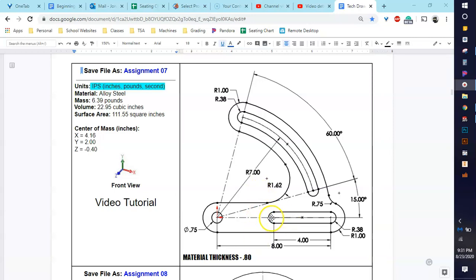So I am actually only going to use the straight slot for this. This portion down here, I'm going to be drawing with just normal lines and arcs. And then this up here is actually a center point. Okay, it's off of the center, but it's an arcing slot. So that's what this is. This bigger piece is also the same thing. And yes, we will trim that. So you'll get to see how, when you're trimming slots, it deletes your relations. So you'll see why I didn't do it down here. But I'm going to do a mixture of the two so you can see both. You're welcome to try this as a slot. Maybe you think, hey, it's not that bad. I'll just tell you that there's more things you have to fix than think through.